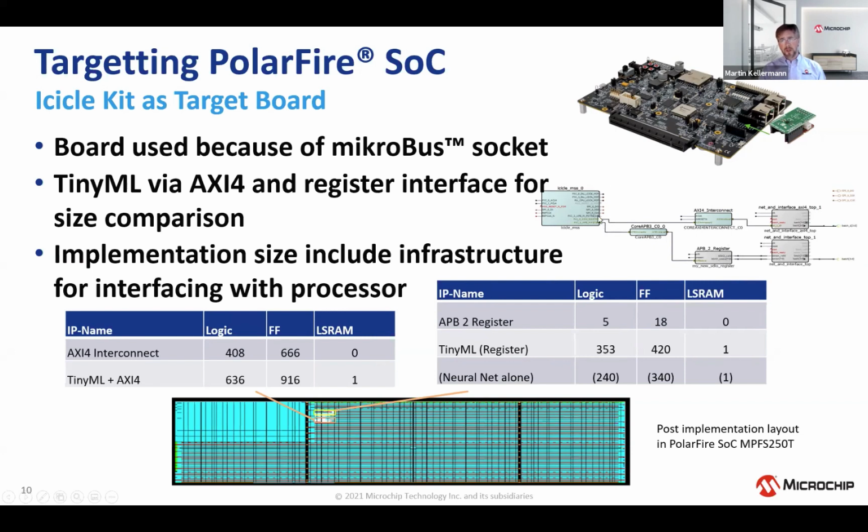The other one is this AXI interconnect, which I can already give you as a teaser, which will be a little bit larger. And then here on the AXI interconnect, I'm feeding that into the deep net. And the output on both is theoretically 8 bits, as I was just putting in an int8 as output. But of that, I only use the bottom 4 bits, and the others I omit in the implementation, then they will just be optimized out.